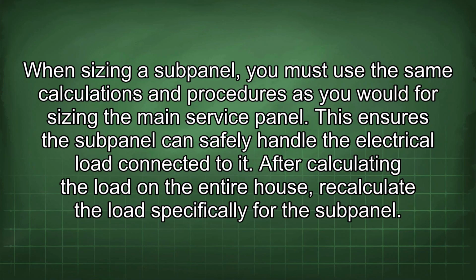When sizing a subpanel, you must use the same calculations and procedures as you would for sizing the main service panel. This ensures the subpanel can safely handle the electrical load connected to it. After calculating the load on the entire house, recalculate the load specifically for the subpanel.